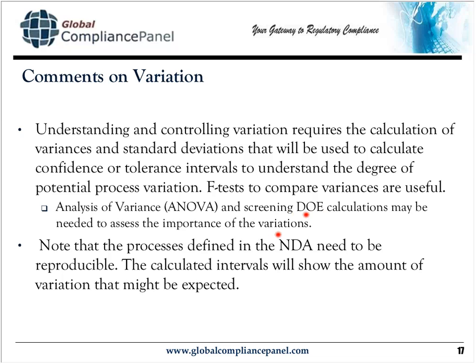Now, your screening DOE, there are some very large scale studies that you can do. And my advice to you is start simple. Don't go into a huge study, 11 factors and all this sort of stuff, because all you're going to do is drive yourself crazy during the initial study. Start off simple. When people get used to working with the simple DOE studies, then you can possibly expand it to larger scale studies.